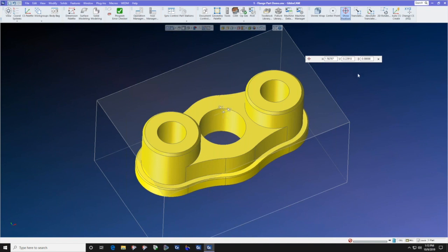If you are on a 4 or 5 axis milling machine, as soon as you move out of plane, X, Y, and Z don't mean anything to us anymore, neither do G2 and G3. But we have HVD, X, Y, Z equals HVD, horizontal, vertical, depth.